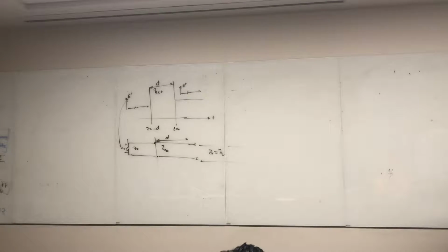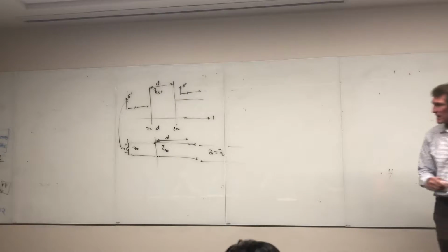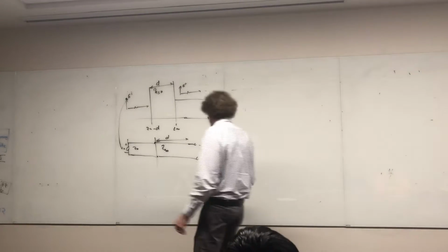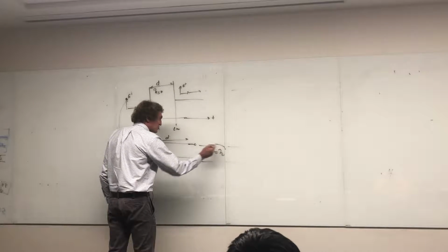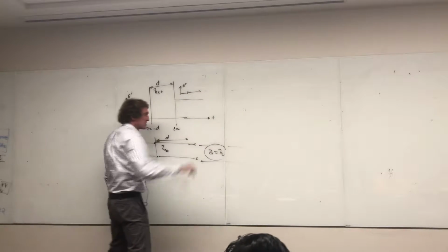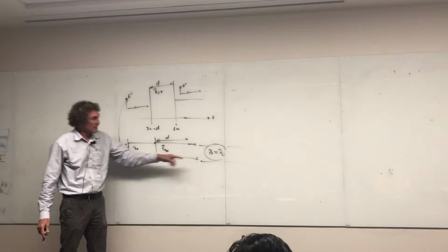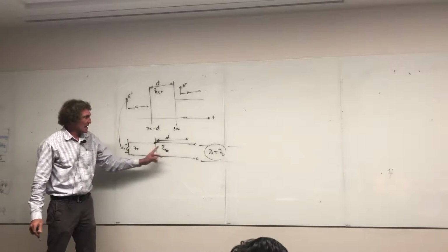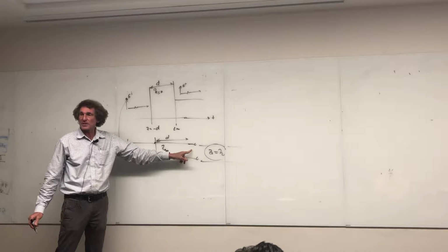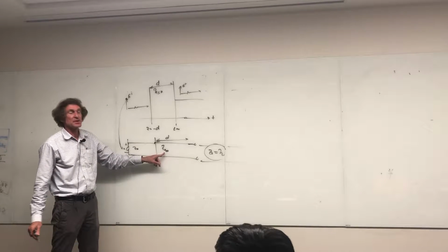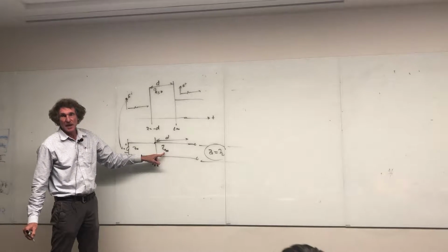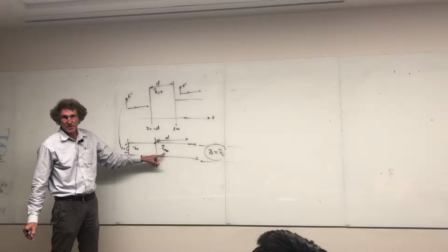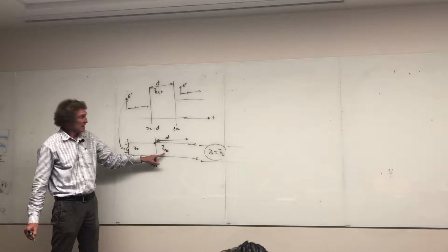He shows this, yeah, he's got that, like this. Now, just follow me on this. This represents all the free space on that side. It goes on forever, so we just put a load there, which is Z0. Here's the actual transmission line, but this is a lossy transmission line, so the characteristic impedance here is lossy. I'm going to put the equation for it. I don't expect you to remember this one, but I want you to see it.